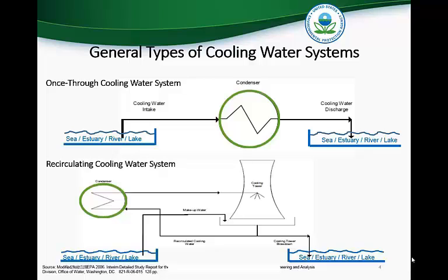A condenser is found in systems involving heat transfer. It's a device or unit used to condense a substance from its gaseous to its liquid state, typically by cooling it. In this case, steam is condensed to water. In recirculating systems, makeup water is added to offset water released by way of evaporation, leakage, and blowdown. Makeup water serves to keep the flow rate constant.